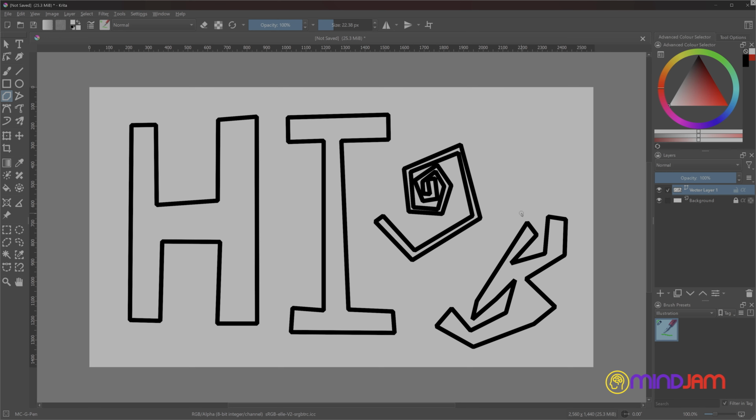6. The Polyline tool works exactly how the Polygon tool works, but you don't have to close the shape at the end. It will end as a line with a beginning and an end. As with the Polygon tool, the Edit Shapes tool will be useful if you wish to create any curves or move any nodes. What's helpful is that you can hold Shift to move multiple nodes at once.